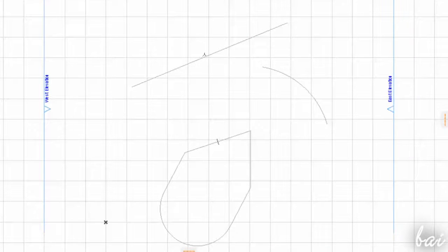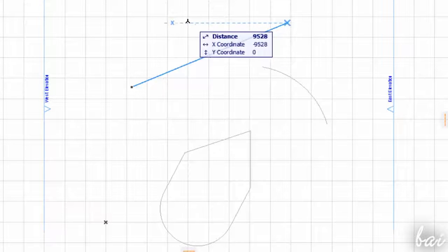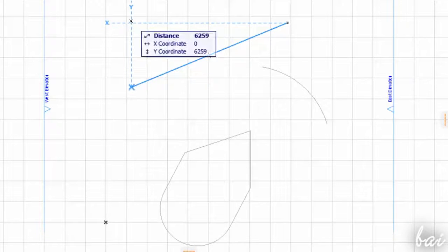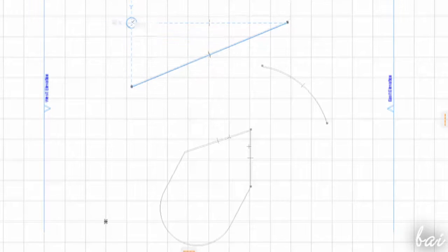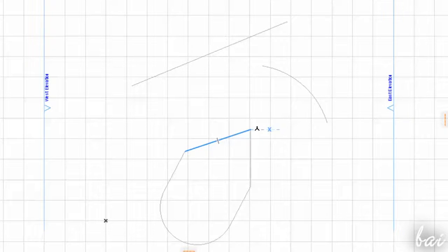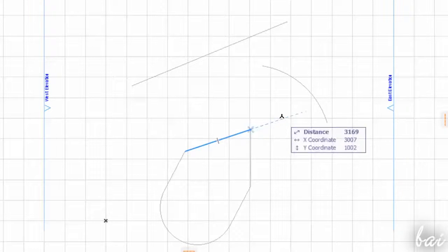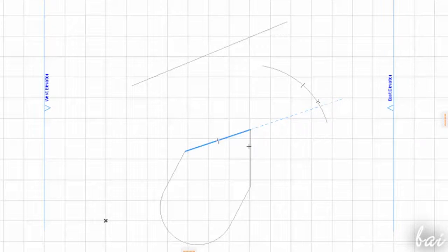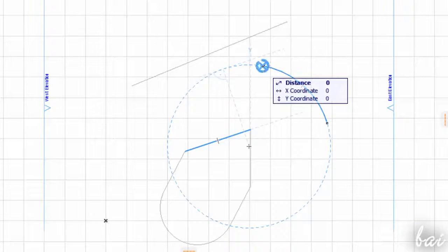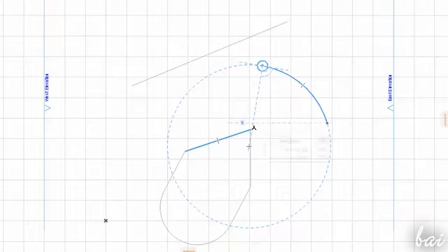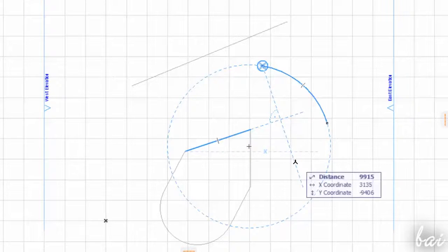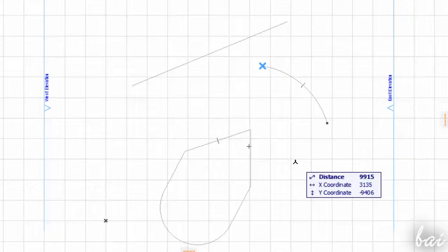New in ArchiCAD 19 is the ability to draw tangent, perpendicular, or along the same direction of one or more elements. All you need to do is hover over the object's path until it is completely highlighted in blue. Then you can very easily draw a line perpendicular, tangent, or following certain directions. Those blue lines are called guides. You can remove all of them using the Escape key. Those lines are never rendered in your final project, of course.